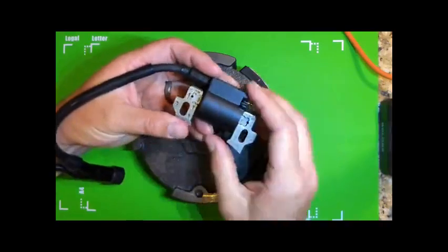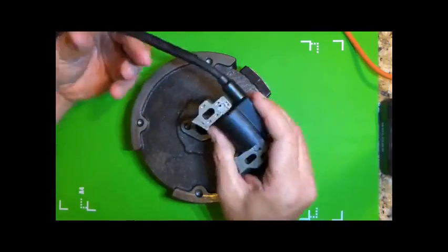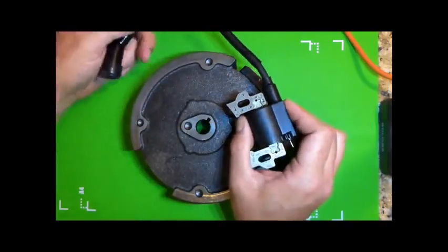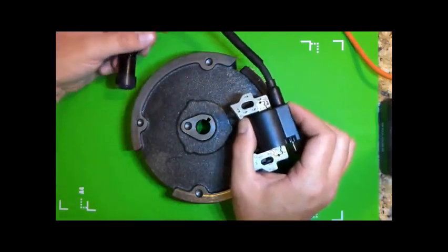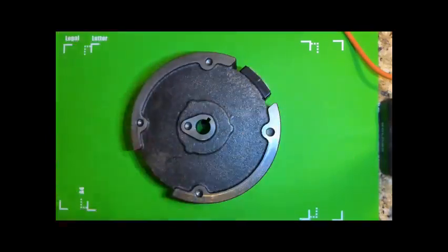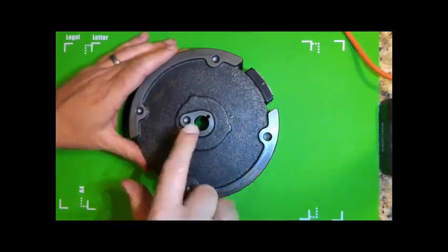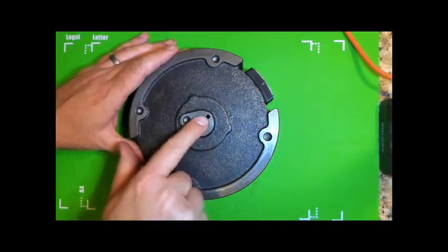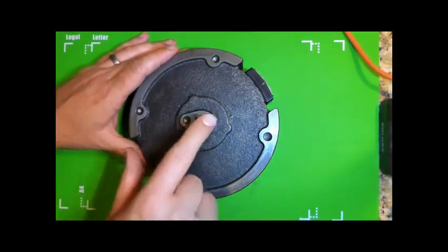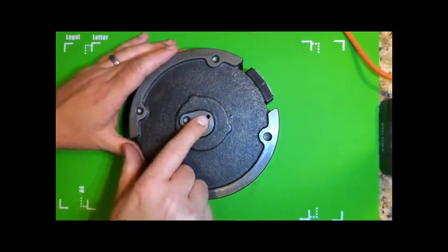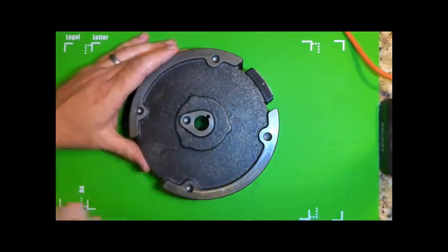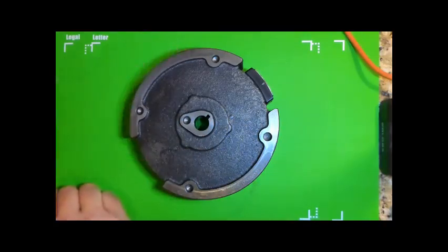That there's a coil of wire in here that's actually going to create a high voltage electrical current to be sent to the spark plug at the correct time. And we'll get into the exact meaning of timing in another video, but the central point of timing in the electrical system is actually going to be the flywheel key, which is going to ride right here, so that we are attaching this flywheel to the crankshaft in 100% the correct place for this to happen.